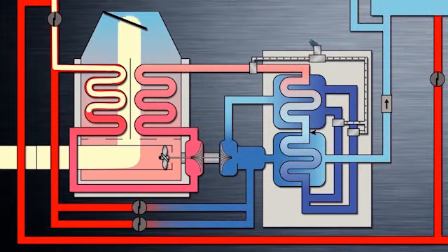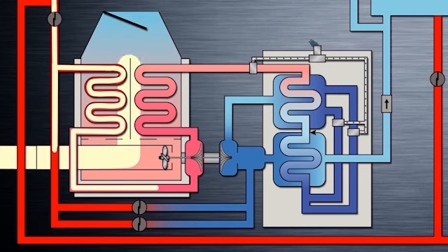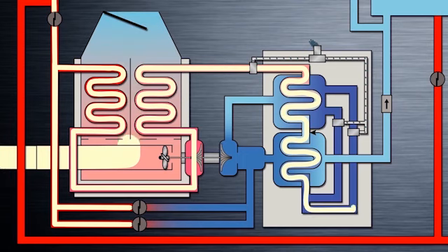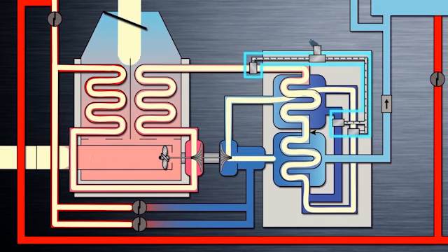Once the initial heat exchanging has taken place, air passes through an air cycle machine that compresses, refrigerates, and sends the air to a second heat exchanger that also cools down the compressed air with the use of ram air. Afterwards, compressed cool air passes through either of two water extraction ducts, where water in the airstream is condensed and falls into a sump, where it's then drained.